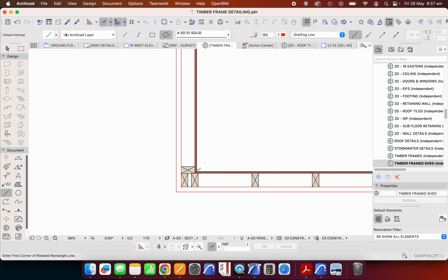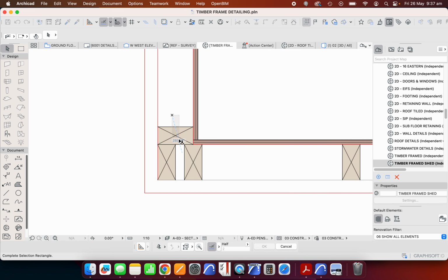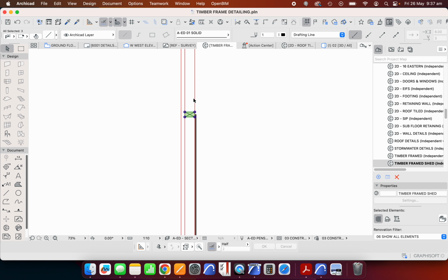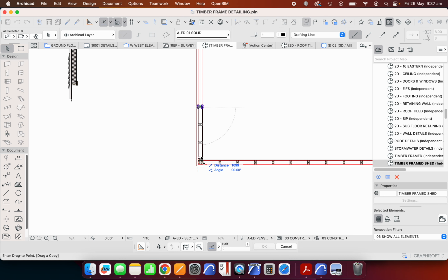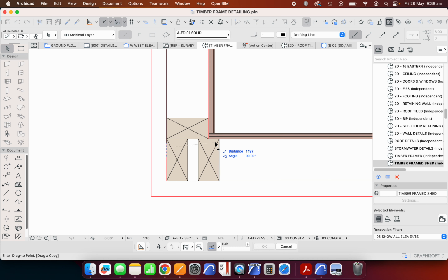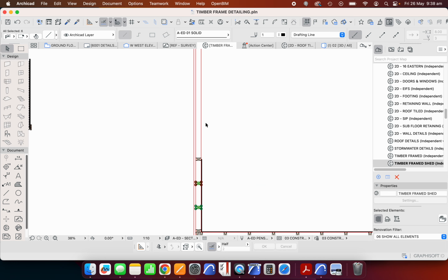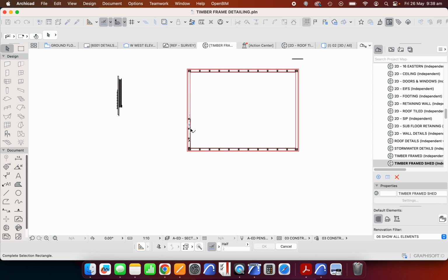So this sheet, let's measure it. We need this sheet to still be 1200 long. 1200, so that's fine. So then we can take this stud, copy it to where? To the center. And I'm going to work back and forward from this point. Move, multiply, 400, 400. Now if I look at this very carefully, if I placed another one at 400, of course it's going to be centered on the middle of the end of the sheet. I don't want that. I'm okay with leaving the other one as it is, so that's why I used that in its position.